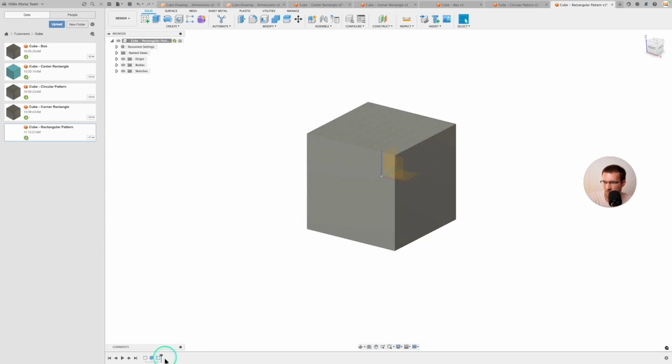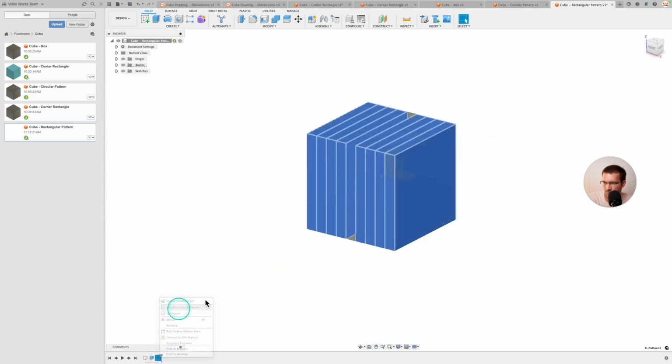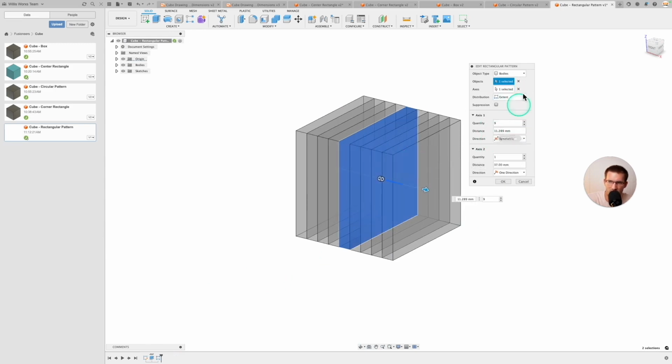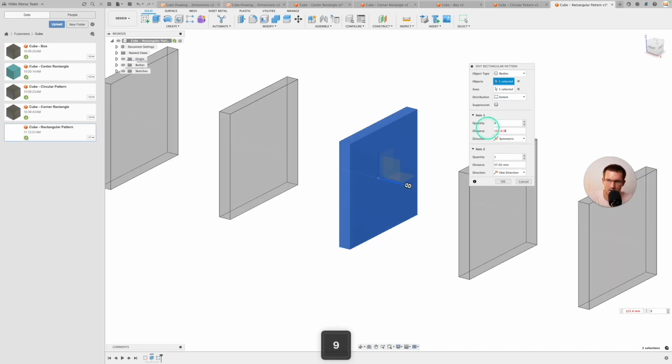And just to briefly show you what I mean by this spacing option, if you change it to extent, you'll see that this automatically updated. So if we go back to spacing, this is our calculation we made when we said 25.4 divided by 9. But if we go to extent, let's do the same thing. We said 25.4 divided by 9.